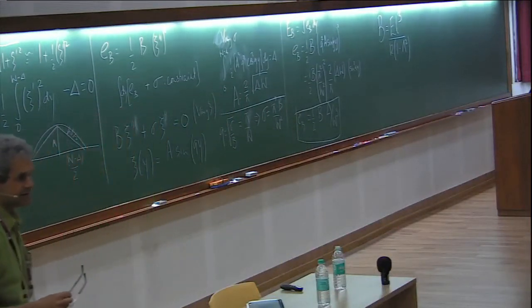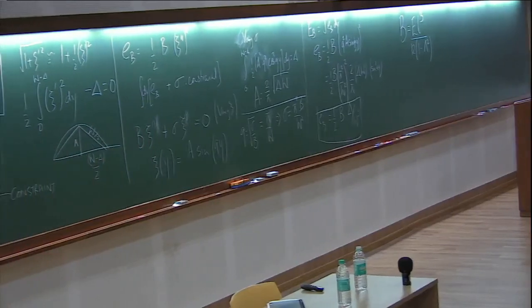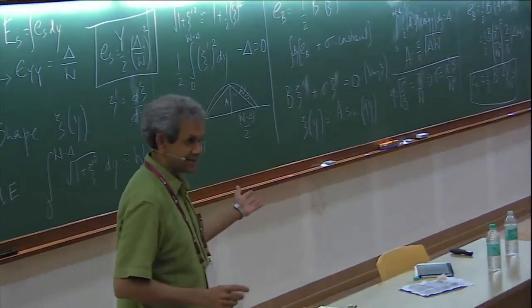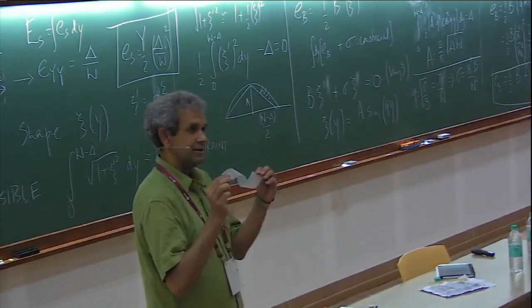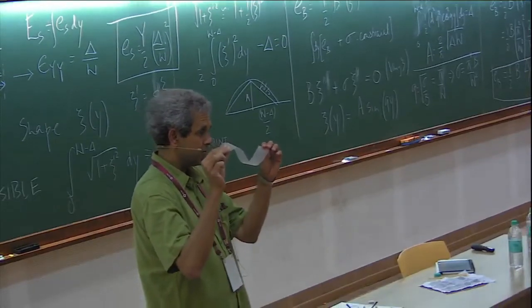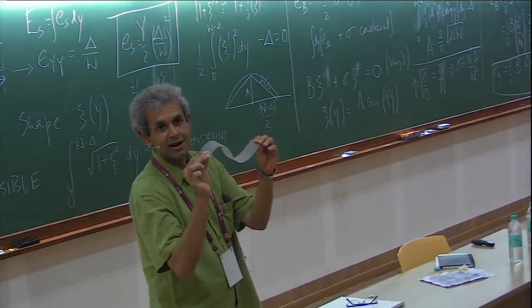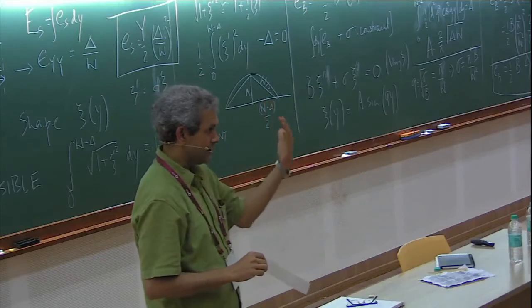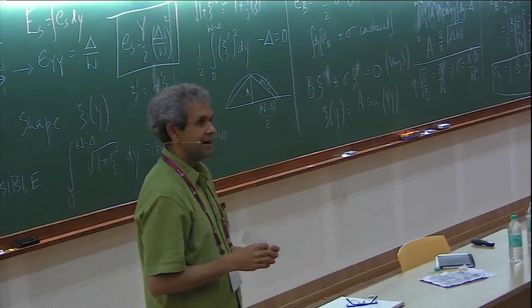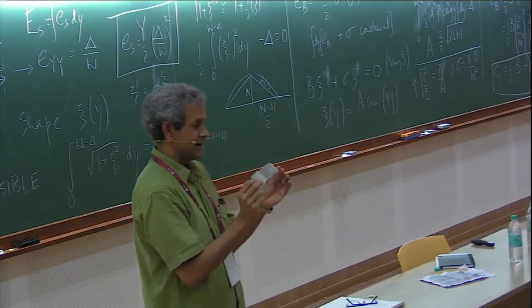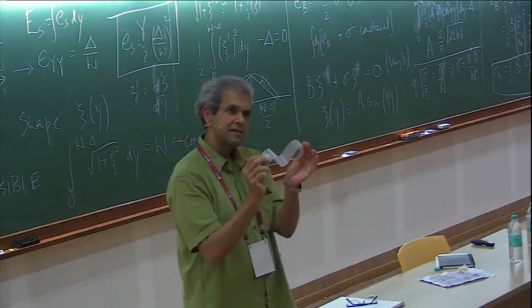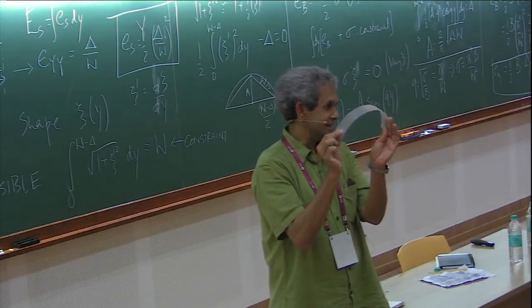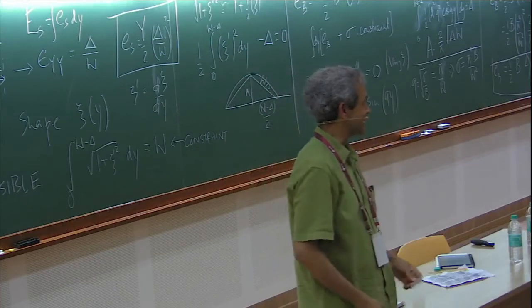In general, it could be a Fourier series, right? So that's something that I would ask you to try. As you can guess, it's not so much more difficult. Here are interesting things to try. Try mode 2. You can almost immediately guess this is more energy, right? I mean, there's more bending going on here, right? So it's going to be a higher mode. You can tell almost by inspection. So the question you might like to answer is, how much higher? But the more interesting question is, is there a barrier between this mode and this mode?